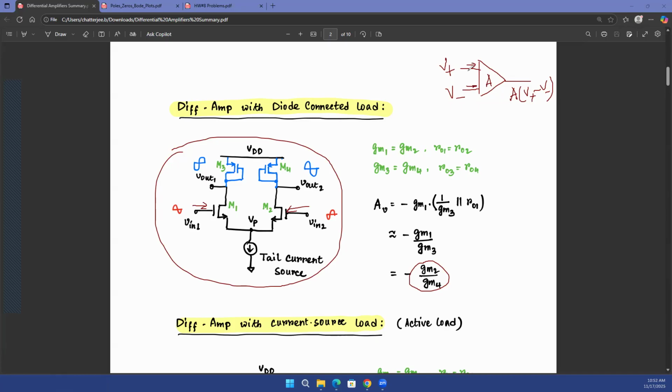However, there are two big differences here. First, the gain of the op-amp is not infinity, it is small. Maybe it is 5, maybe it is 10, but definitely not infinity. The second difference is that for the op-amp, whenever you drew an op-amp earlier, you always had two inputs and one output. We still don't have that. We have two inputs and two outputs in the differential amplifier circuit. So how do we eventually get to a scenario where our overall configuration looks similar to an op-amp, and of course try to have infinite gain at some point and so on.